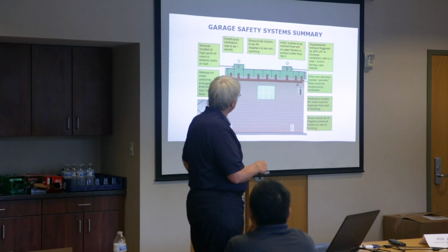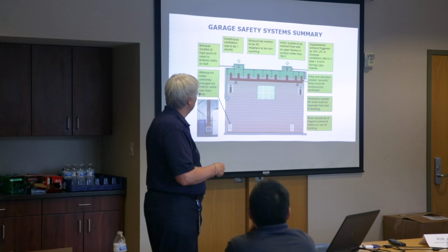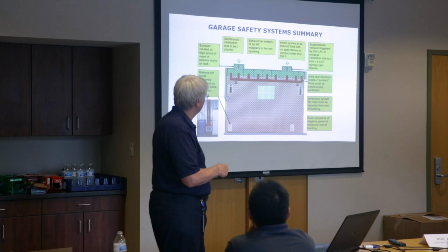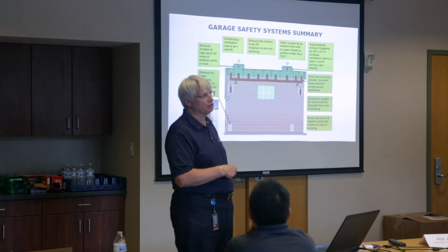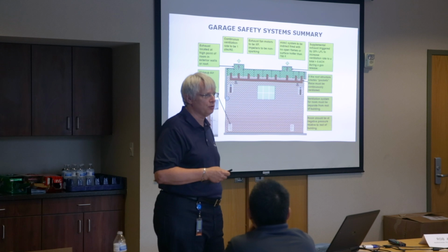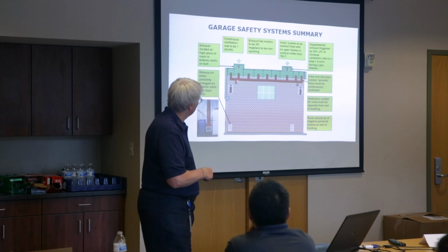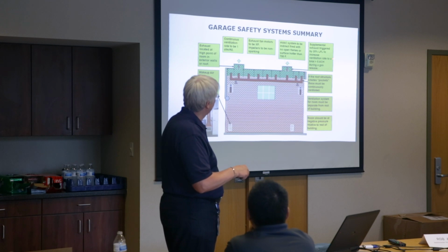So the HVAC system can be indirect fired, but there needs to be no open flames, and we have to have no surface hotter than 750. Again, just those requirements that we went through in NFPA 30A, to remove that ignition source. We also have supplemental exhaust, so our second fan over here is our supplemental exhaust fan.